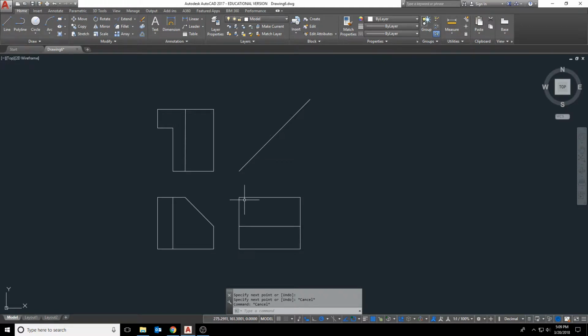So basically for this hole, we're going to have to do some fancy work. The dimensions that are on this, it is dimensioned off of this bottom face at 18 up along this angle. And if we take a look at what the total length of this is, it's actually 39.598. The 18 that they're specifying is basically trying to put this in the center of this.